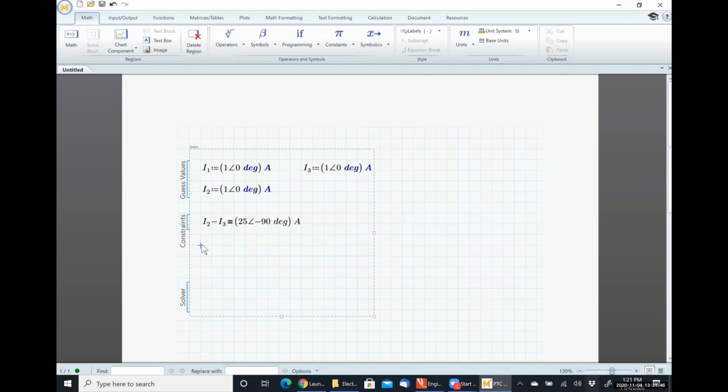My second equation, gosh, let's see, that was J2, which I can put in MathCAD as either 2i or 2j. Either way works perfectly fine, but if I do J2 by itself, it will freak out. So put the same as when you're using your calculators, put the imaginary operator after the number. This is ohms multiplied by I2.